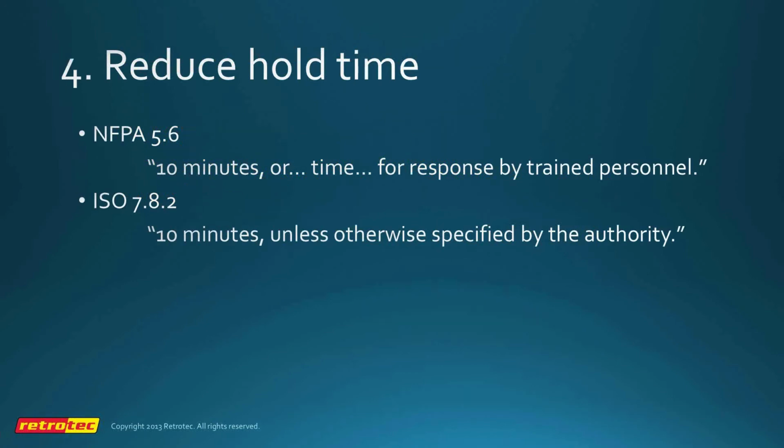Both NFPA and ISO specify 10 minutes, but they do say, unless otherwise specified by the authority, generally the authority goes along with whatever the design is, although some of them tend to focus on it being 10 minutes regardless. But particularly for small enclosures, a case could be made for sometimes having only a 5-minute retention time, or even 2 minutes if the enclosure is very, very small. Getting small enclosures tight enough to pass hold time is probably the single most difficult problem that enclosure testers face.